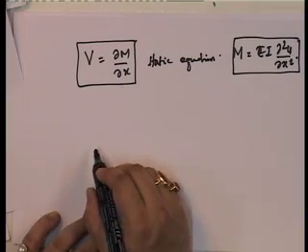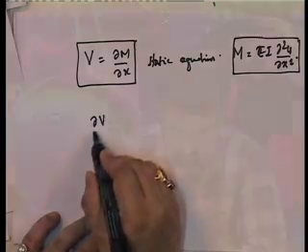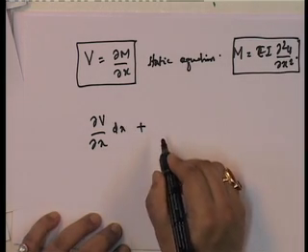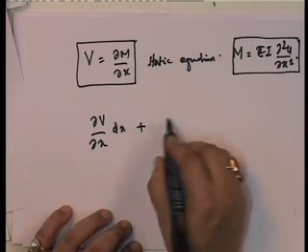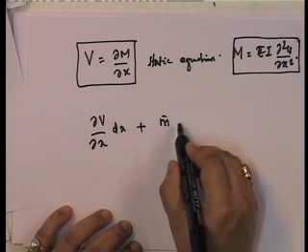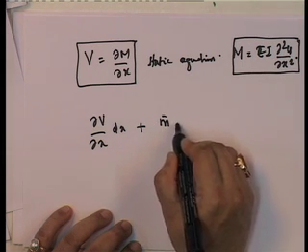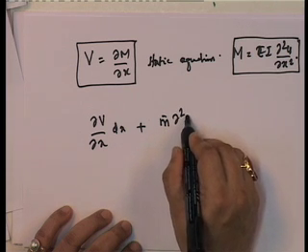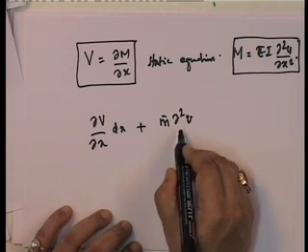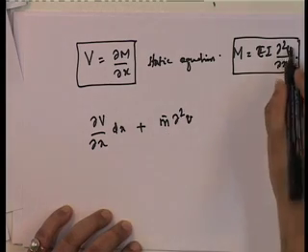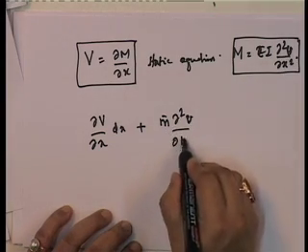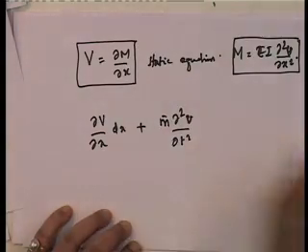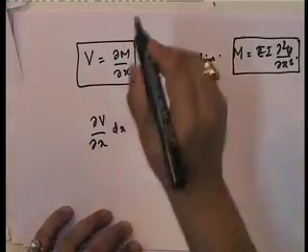It gives us del v by del x into dx plus f I. And what is f I equal to? F I is equal to m bar into del squared v by del t squared, because v is in this direction, u is axial deformation, this is lateral deformation.